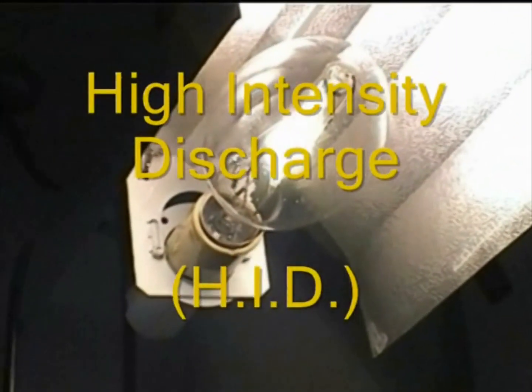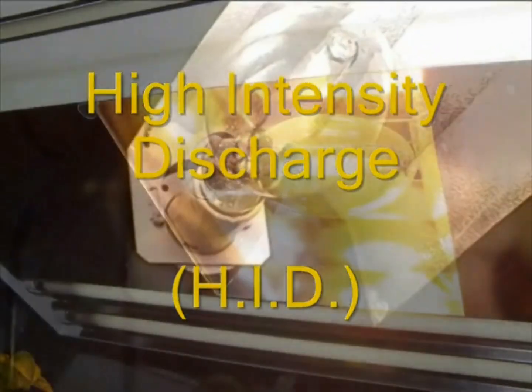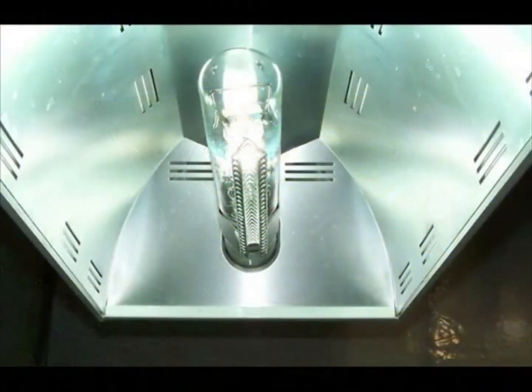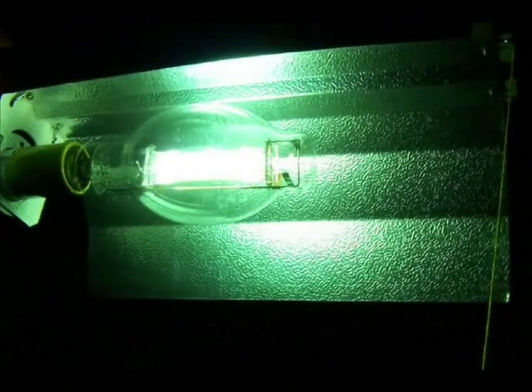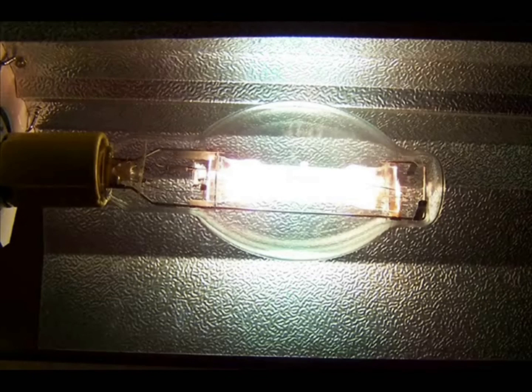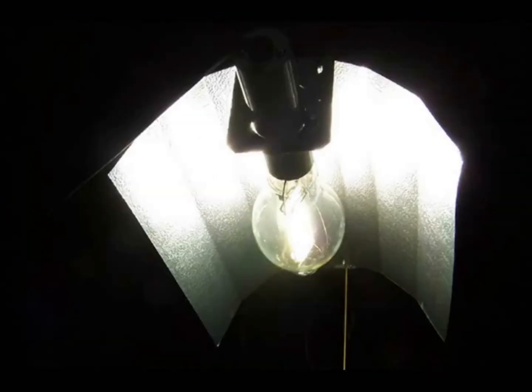High-intensity discharge lights provide powerful lighting at various frequencies. The light bulbs themselves consist of a gas or vapor-filled sealed chamber surrounded by an air-evacuated glass envelope. The intensity of light radiation from these bulbs at any wattage creates very intense heat. Caution must be used when operating these lights. Do not touch until completely cool, and do not splash with water under any circumstances. A water splash could cause a hot bulb to shatter.